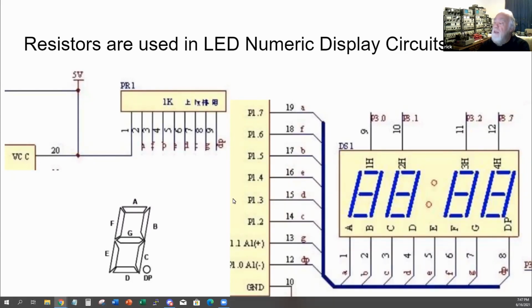So the processor, in writing all this data, has to go through a fast loop over and over again, each step of the loop calculating what the bit configuration is for the digit, and then writing it to the segment leads, and then illuminating that digit for a fraction of a second, then moving on to the next one over and over again to display all 4 digits.